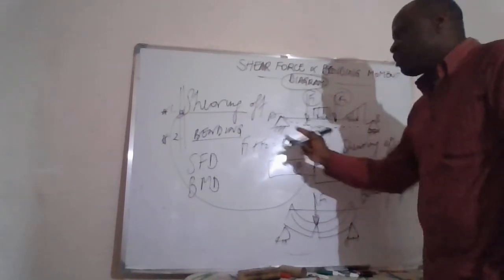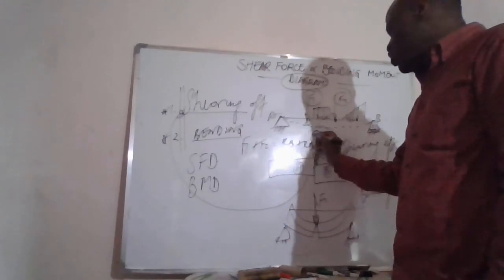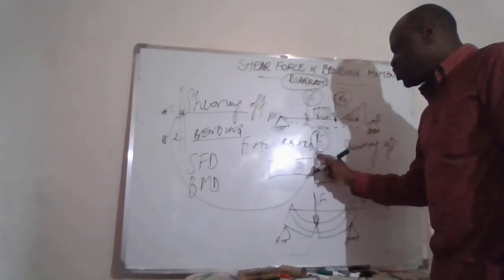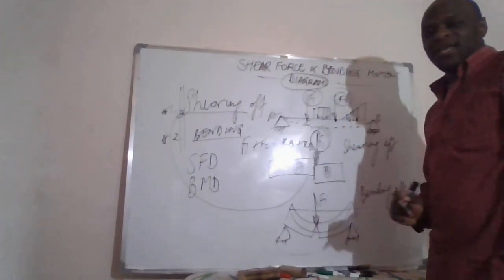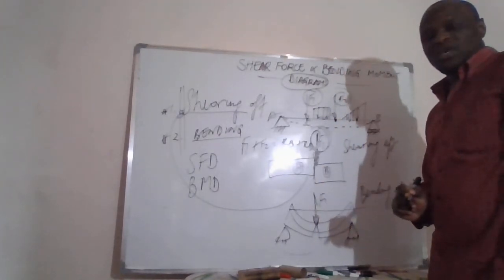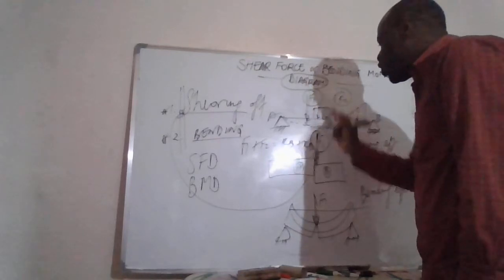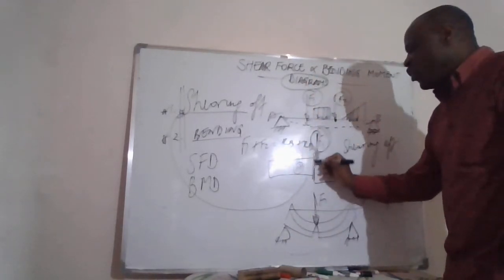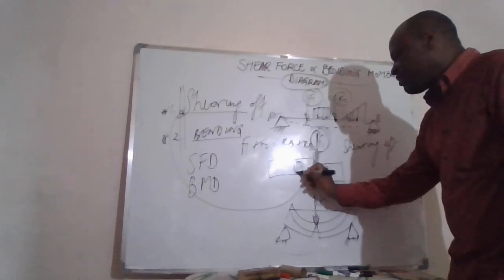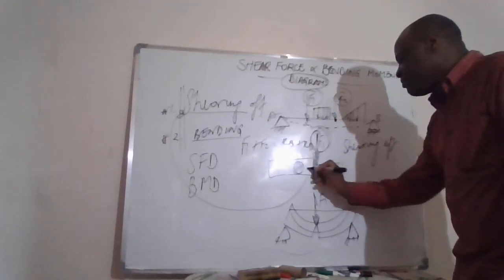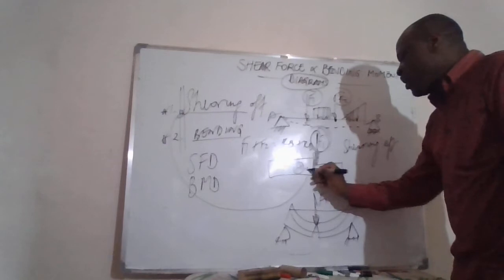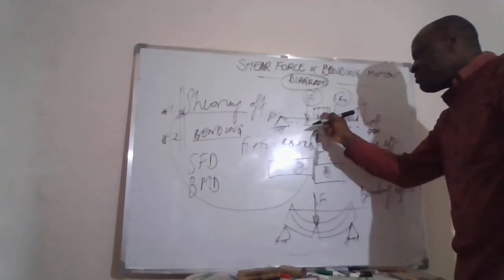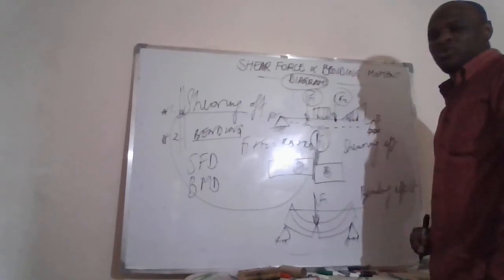Now, what is a shear force then? A shear force is the effect of the force trying to shear off the beam, and that is called the shear force. It's that force due to the load that has an influence of sliding one portion of the beam over the other while the load is applied, either the distributed load or the point load.